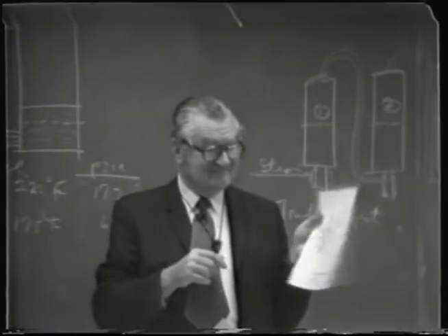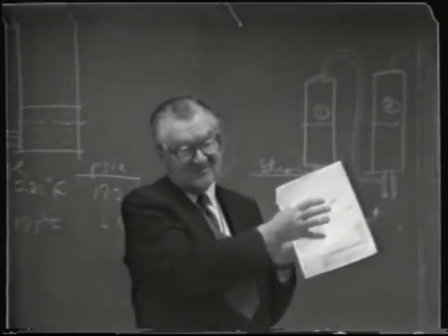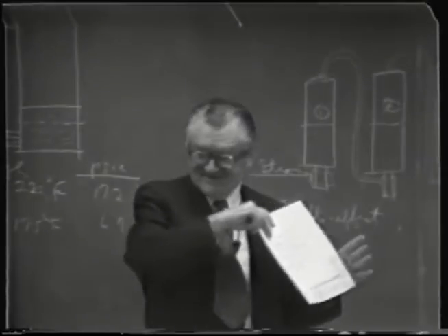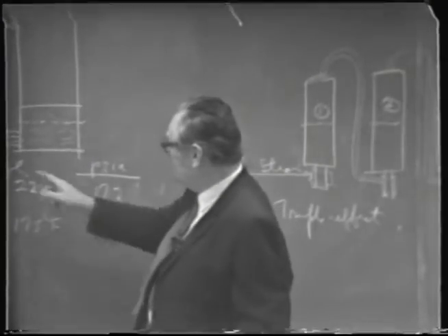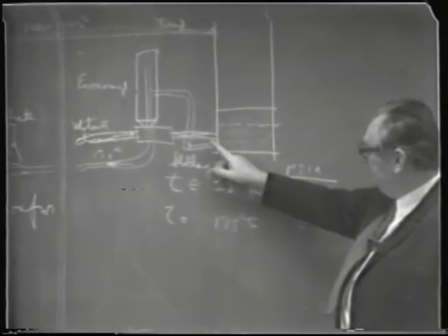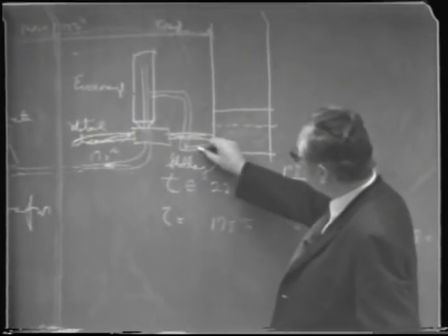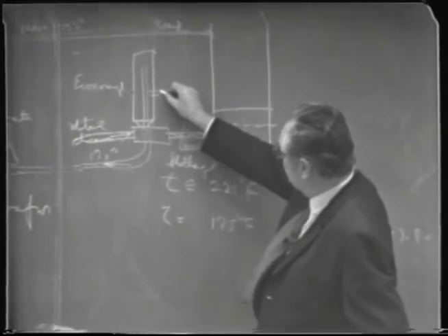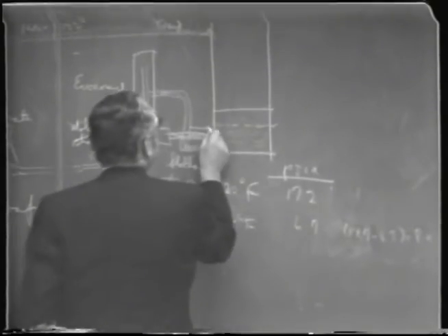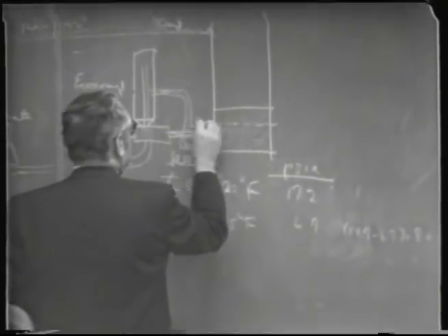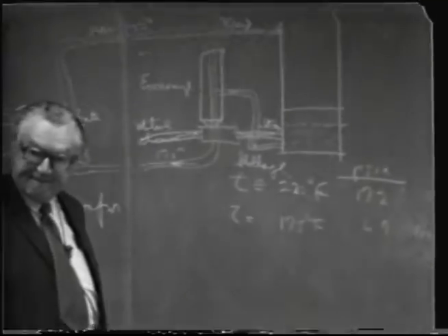The diagram isn't real clear as to which goes to which. No, the diagram is a little bit confusing. It's how it looks on the outside, not how it looks on the inside. What's the line going over between? Well, this is a very crude sketch, but this represents the stillage going out here, and the stillage going in here, and this represents the steam going into the still, which includes the motive steam plus whatever is flashed off and mixed with it.